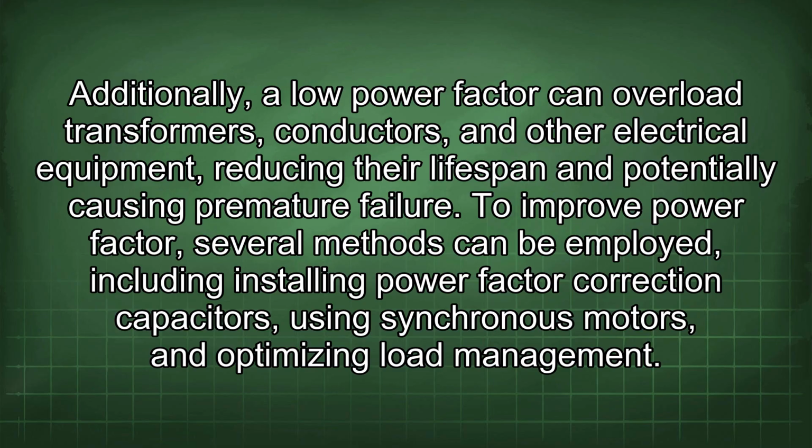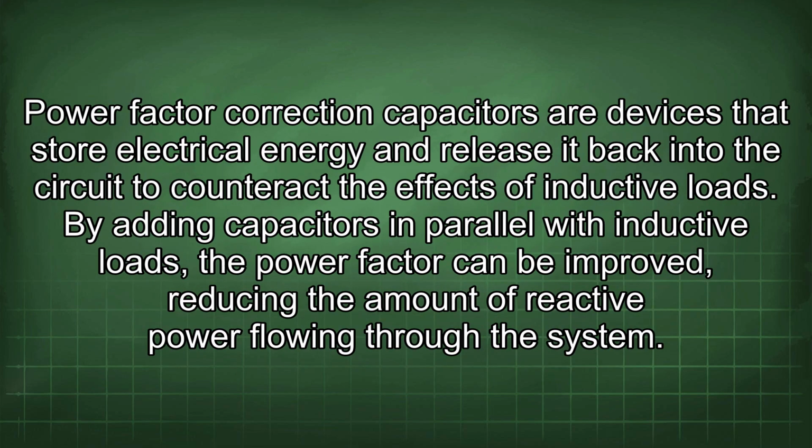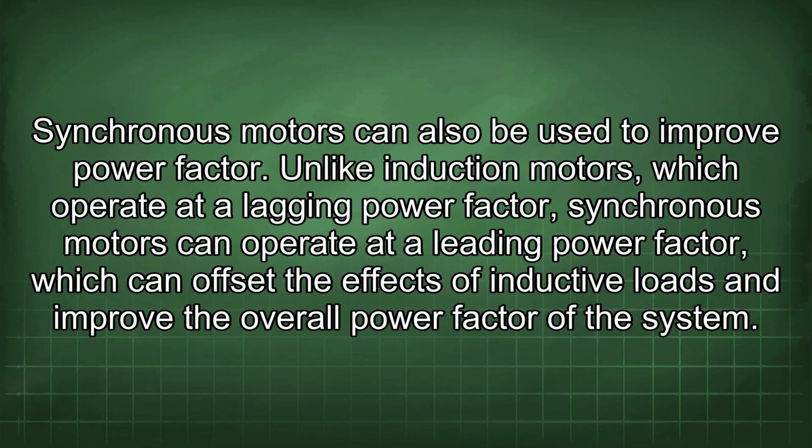Power factor correction capacitors are devices that store electrical energy and release it back into the circuit to counteract the effects of inductive loads. By adding capacitors in parallel with inductive loads, the power factor can be improved, reducing the amount of reactive power flowing through the system. Synchronous motors can also be used to improve power factor. Unlike induction motors, which operate at a lagging power factor, synchronous motors can operate at a leading power factor, which can offset the effects of inductive loads and improve the overall power factor of the system.